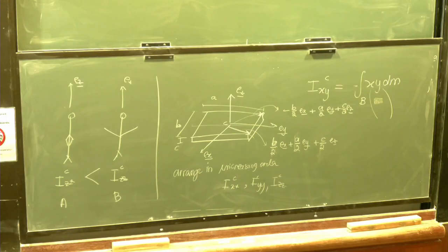Linear algebra, I remember linear algebra. Yeah, eigenbasis, right? So whenever the products of inertia are 0, the basis you're looking at, the rotational basis vectors, are eigenvectors. So you can always find an eigenbasis for the inertia tensor, or the matrix representation of the inertia tensor. Okay? Questions?